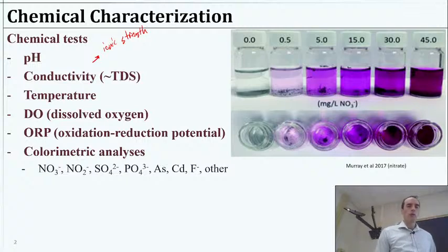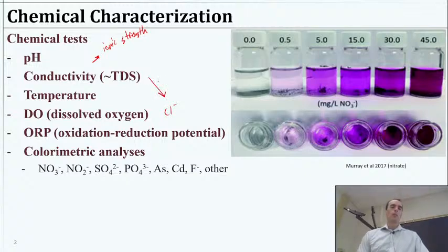There are a few other things that affect the amount of oxygen that can dissolve a bit. For example, chloride concentration does impact the amount. So if you have a lot of chloride, I think that slightly decreases the amount of oxygen that your water can take. It's not a big effect, but it is an effect. So if you make some assumption from total dissolved solids, you could get some estimate, okay, we expect to have this amount as our saturation value. And look, we're 3 milligrams per liter below that, so clearly something's demanding oxygen, where we've been oxygen deprived.